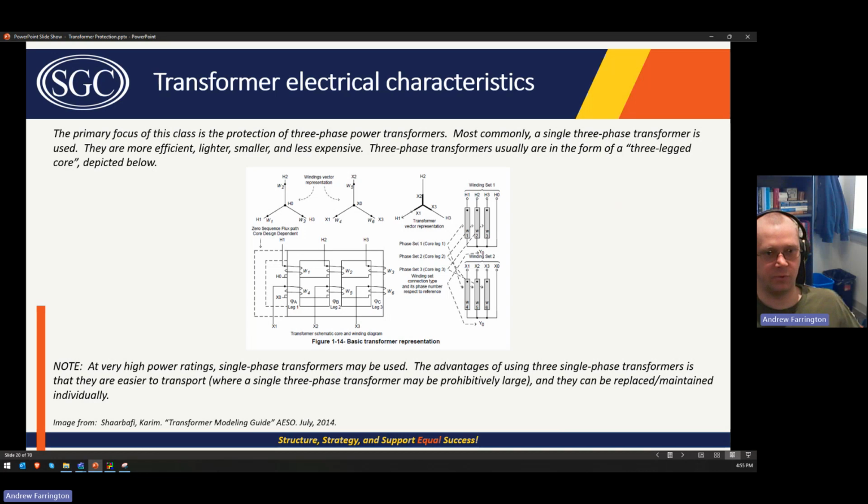The other reason for transformers of that size to be single phase is for redundancy, because if you have a transformer that size, it's probably pretty important to your system. What you can do is put 4 of them together and connect 3 of them with your transformer winding configuration made up outside of the transformer tank. And then if one fails, you can reconfigure those connections, whether it's reattaching new bus work, or maybe it's already connected and you just have to close some switches to swap it out.